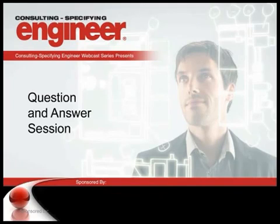I know that's ambiguous, but all the major manufacturers do have a relay inside their controllers that have a curve just like a breaker. Some of them are available even in the standard modeling software, like SKM or something like that. You can actually get those curves and use them in your coordination plots, which I did allude to. And I know, for example, there's a DEC 550 from one of the manufacturers, and then the AMP Sentry from Cummins. You can model them and compare them to your curve. It is important to know that information and check it, because sometimes it does conflict with your coordination study.